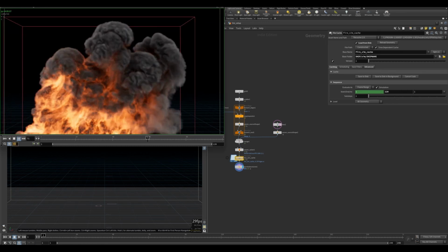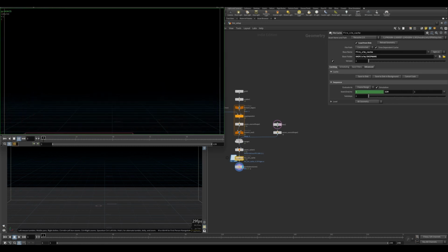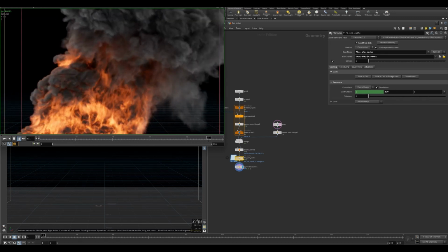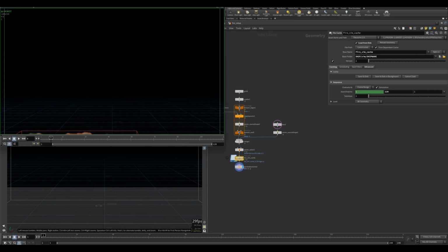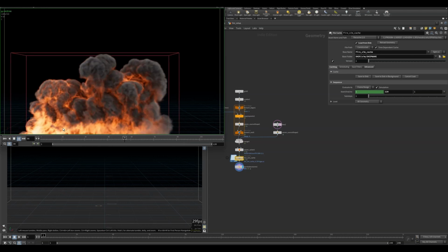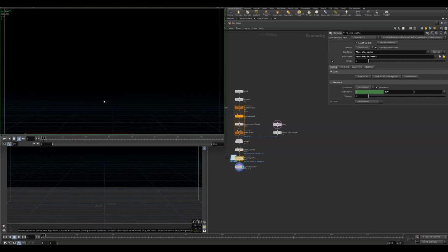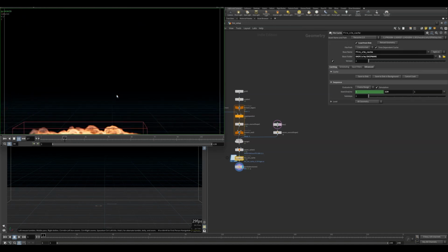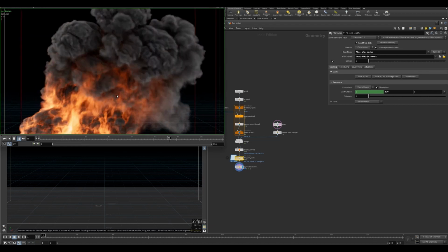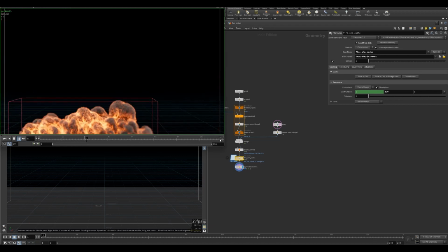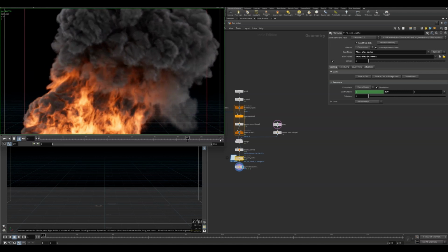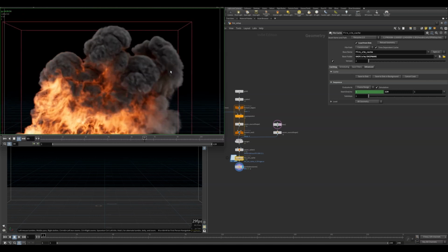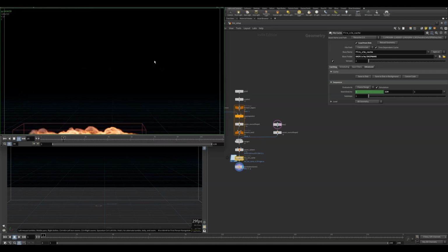As I mentioned before, I'm going to increase the speed by 25%, making it approximately 30 frames per second. So it goes a little bit faster, and this sort of plume thing actually looks much better. Originally in the video, I started my simulation at frame number 120, because I wanted to give myself enough time so that the fire looks like it's already there and going on.